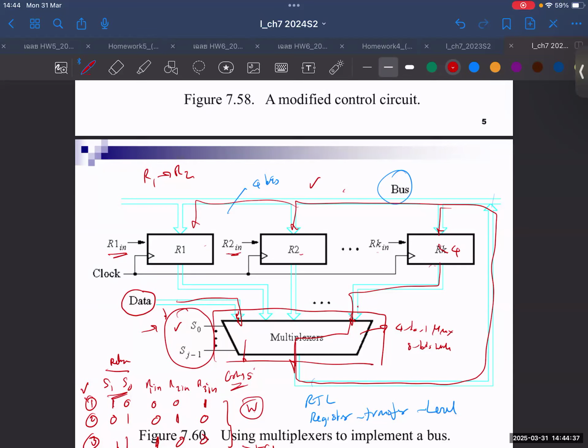And the third one is to understand the tools. Why is that? Because the tools are different. When you want to use the tools from Altera, or you want to use the tools from Xilinx, the Xilinx software, even from the same company, they are different. You understand the tools, and sometimes you can control the tools, how they are going to generate hardware too. For example, in some designs, you may want it to be as small as possible. You want to save area because you don't have much space. You can actually control that in the software by setting some flag, right?